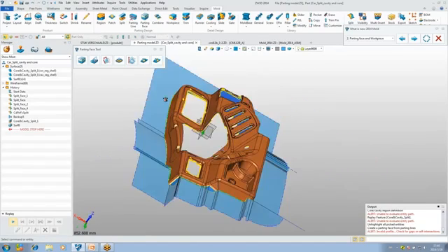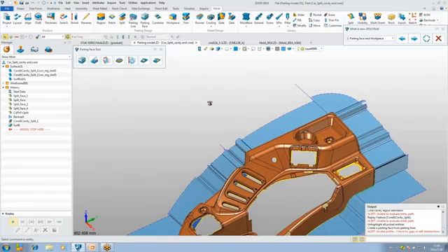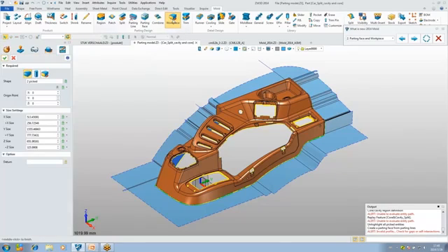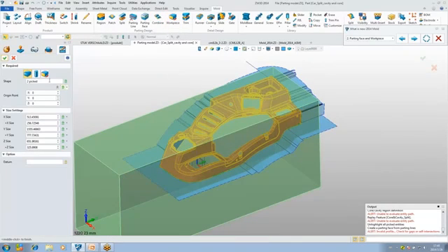Another new improvement is the workpiece, like what I said just now in the PowerPoint. Let's click the workpiece. You can see that, except for the extrude-from-sketch function, ZW3D supports using a block and cylinder to create a stock size, so that you don't need to create a 2D sketch first.